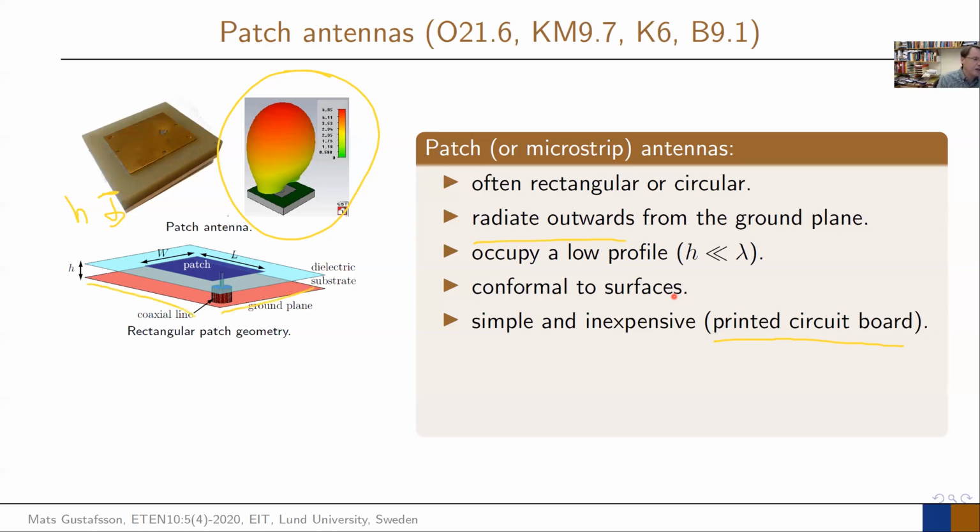So that is one metallized surface. Then you have some material that sits here, that is this dielectric substrate. You will use a substrate called FR4. It's like a plastic material. And on top of it, up here, you also have metal.